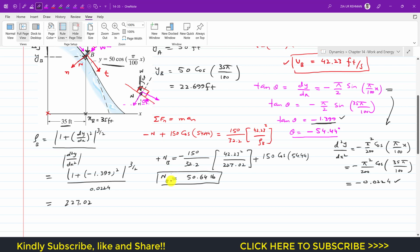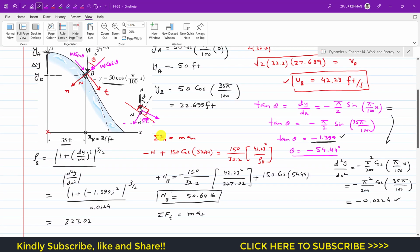Now we are also required to find the rate of increase in the speed. So we have to find the tangential acceleration. For that we have to apply the summation of forces along the tangential axis, and that would be equal to m a_t. Now from the free body diagram we can see that along the tangential direction we have the sine component only. So we have W sine of theta, so we will write plus W, and W is 150 sine of theta, and theta is 54.44, and this will be equal to the mass. So mass is 150 divided by 32.2 into a_t.